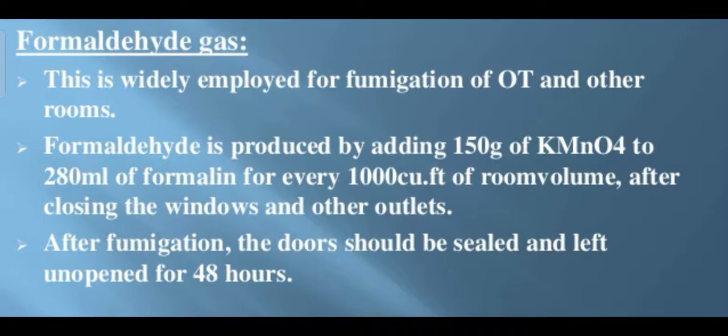Disadvantages of formaldehyde gas sterilization: the vapor is extremely irritating to the eyes, weak penetrating compared to EO, that is ethylene oxide, operates on higher temperature than ethylene oxide. Formaldehyde residue can remain on the sterilized goods if the rinsing phase is not 100% efficient. This can be harmful for the patients. Formaldehyde gas sterilization method is not approved by FDA and only recognized in some countries.